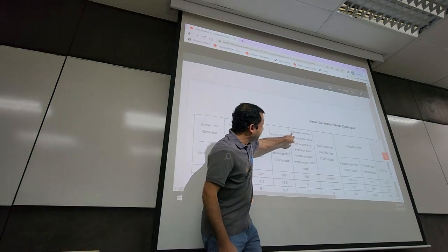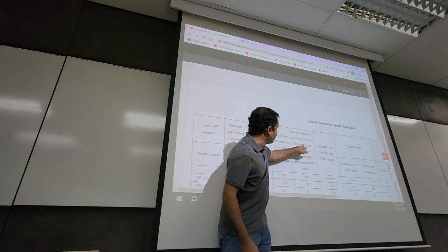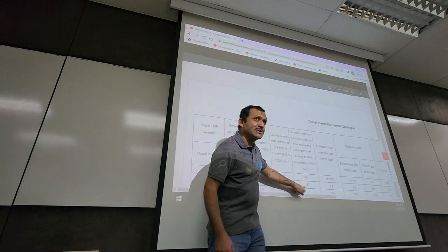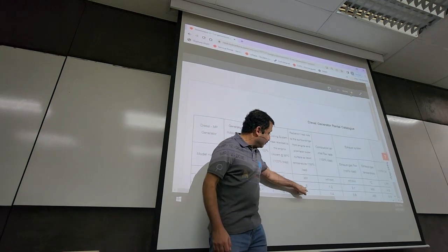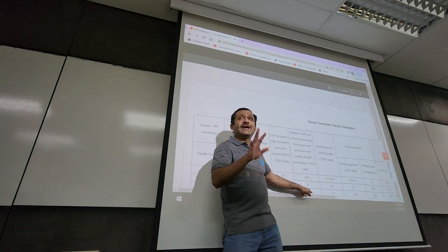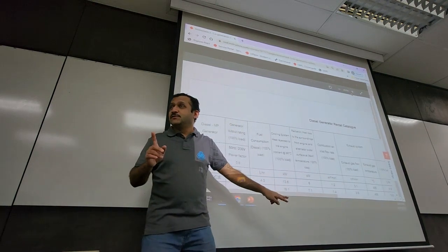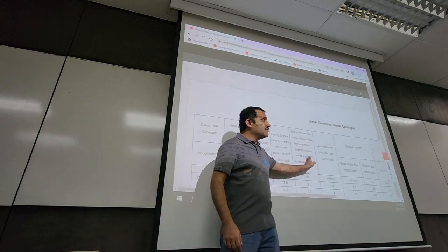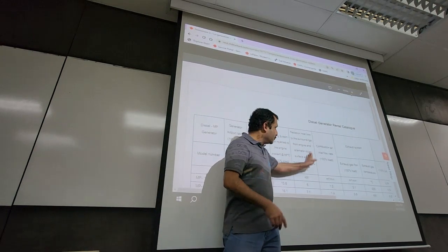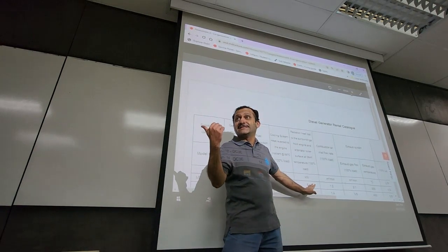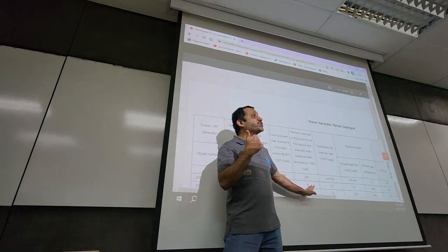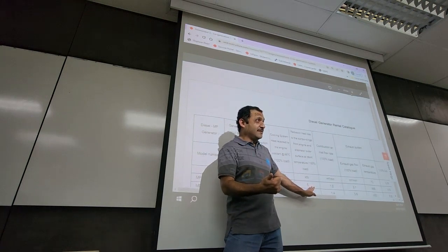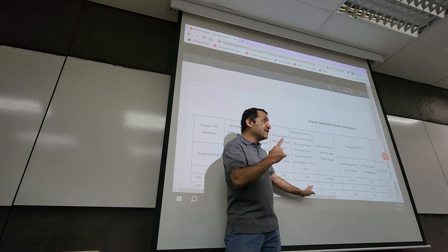that column, radiation heat loss to the surroundings in kilowatts. That value in that column, we cannot use that for heating water. So in the first part of the question, which is the energy balance, this is of no use, but you would need that for exergy analysis to find exergy destroyed. Okay? And we will talk about exergy tomorrow.